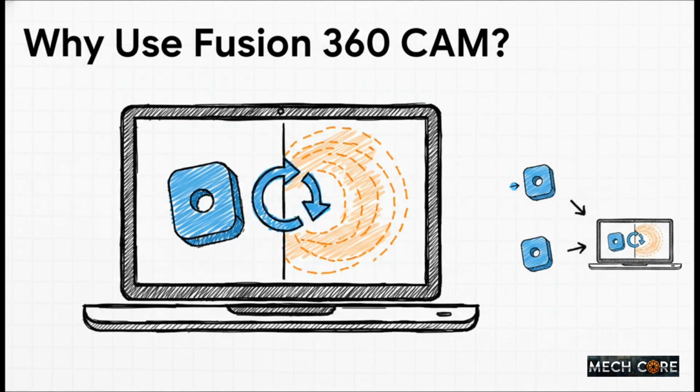Now, you might be thinking, doesn't my machine have its own software? Yeah, a lot of them do, but there are some huge reasons to learn how to do this inside Fusion 360. For one, it's free for hobbyists, which is awesome, but the real game changer is that your design and your cutting instructions are all in one place. So if you want to change the design, no big deal. You just tweak it and hit Regenerate Toolpath. You don't have to start all over. It is an incredibly powerful workflow.